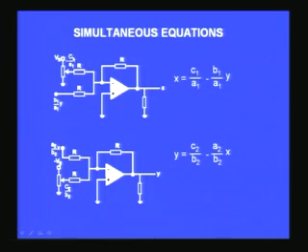So if I give minus c1 by a1 times some voltage into 1 volt, for example Vs is 1 volt, I will adjust the potentiometer here such that I get minus c1 by a1 voltage. If I get that, you would find when it comes here it will become plus c1 by a1, because the gain factor in this is 1, R by R, and therefore I will just get the first term x equal to c1 by a1. But there is also another additional term, and to obtain that I have used b1 divided by a1 times y, the other variable.